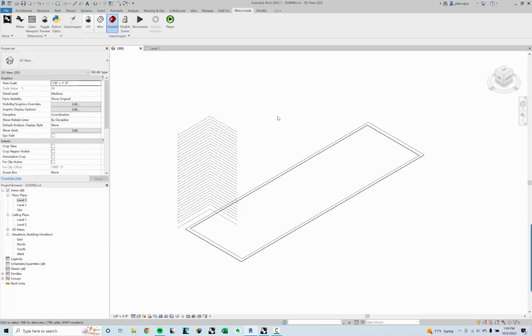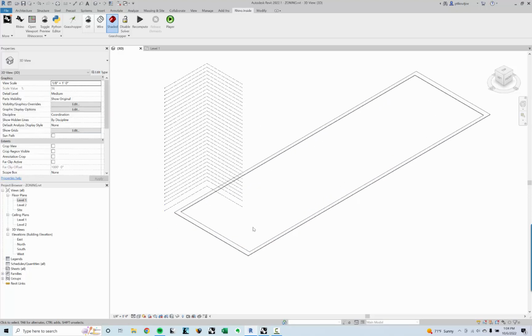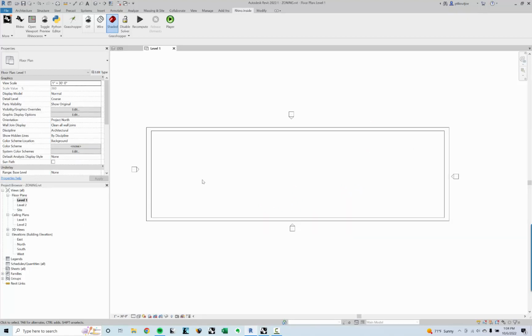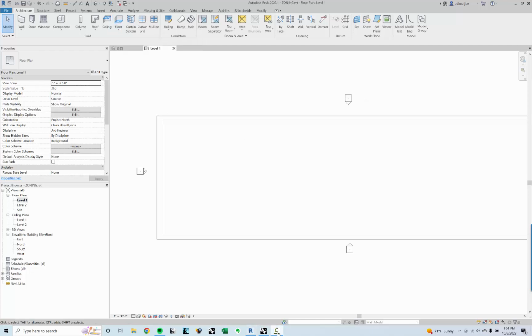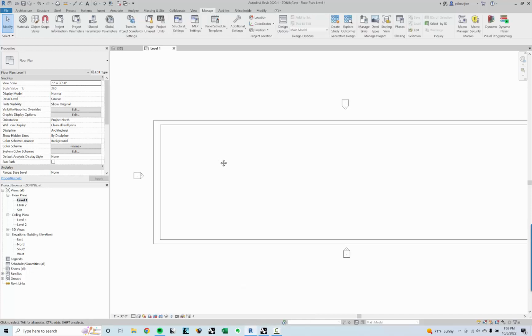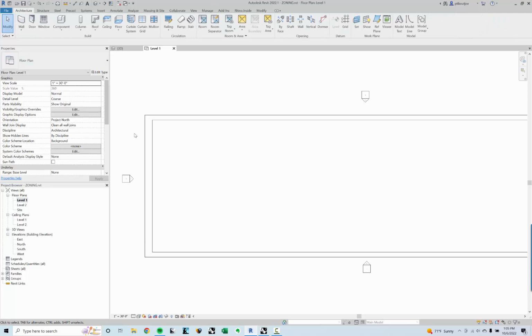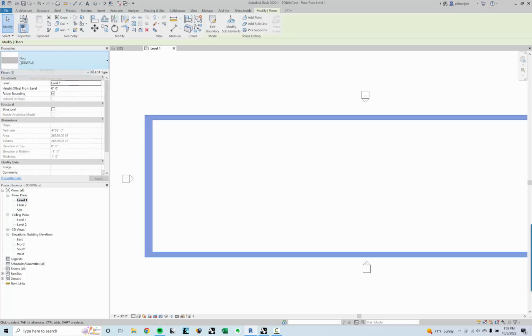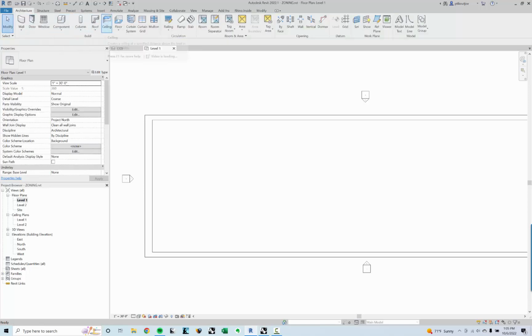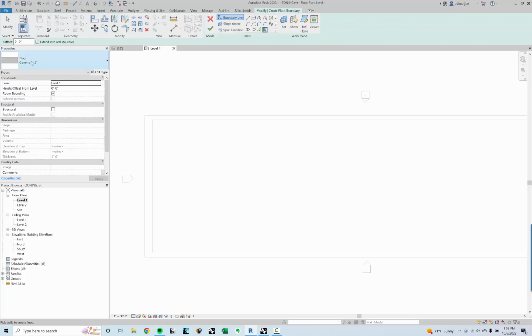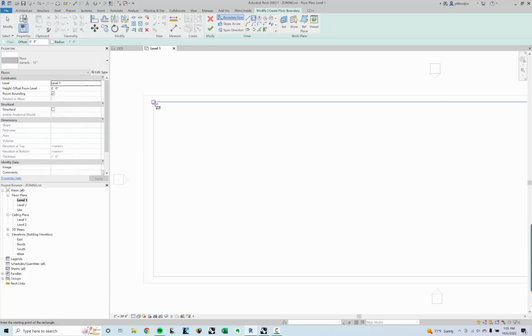And what I'm gonna do is get some floors in here, and we'll just start with some preliminary floors. So if I go into architecture, in my ground floor plan here, I've created this, and I'm just calling this a sidewalk, and then I'll just use generic floors for the next phase here. So I go to floors, I'll use a 12-inch generic floor, and then I'm just going to start modeling these out.